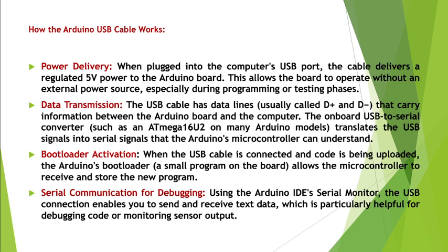Data transmission. The USB cable has data lines, usually called D plus and D negative, that carry information between the Arduino board and the computer. The onboard USB to serial converter, such as the ATmega16U2 on many Arduino models, translates the USB signals into serial signals that the Arduino's microcontroller can understand.